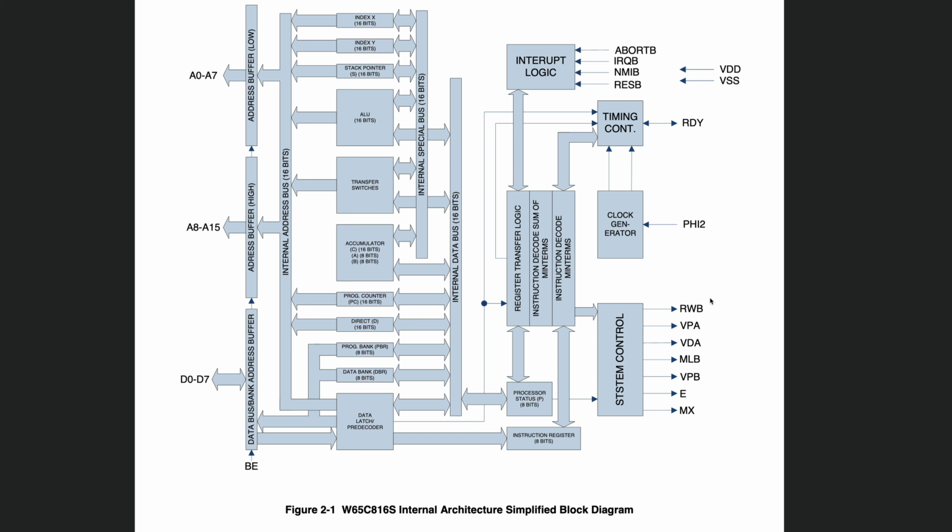There are two ways of stopping the CPU. The first one is just to use the reset pin, and that can certainly work. You can reset the CPU, disable the buffer, do what you want with the bus, and then re-enable the buffers and release the CPU from the reset state, and so it starts running again. The other pin that you can use for that is the ready pin. And that's going to be the subject of our next video.